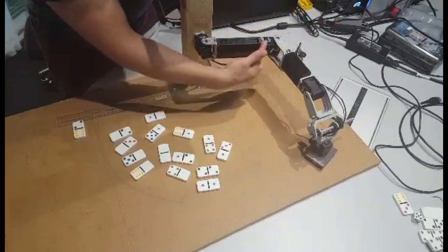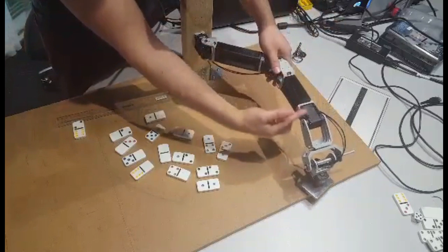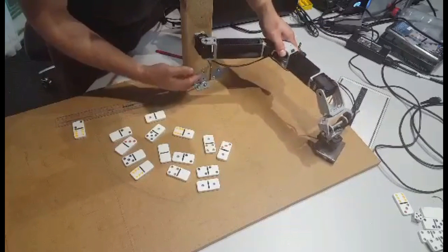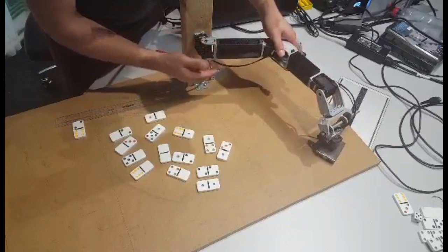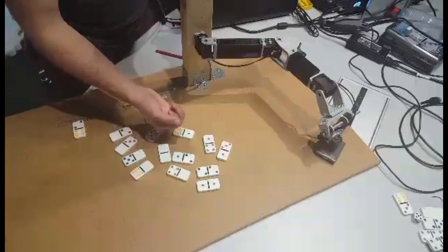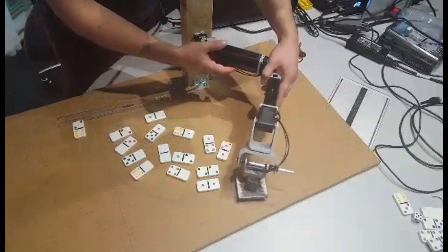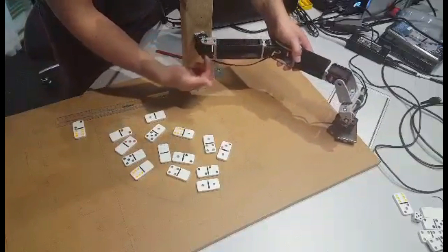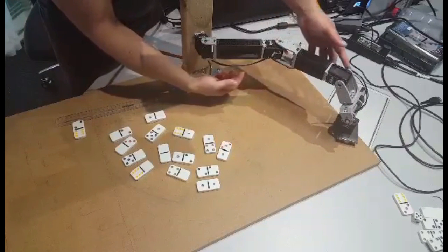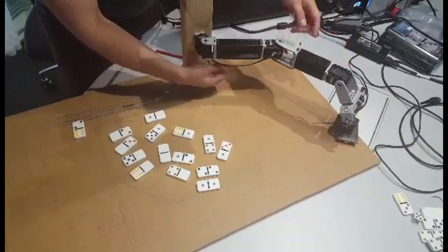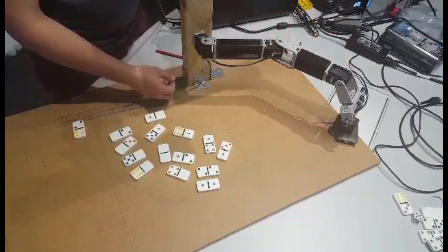Two 3D printed X-beam pieces were designed for having a symmetrical moment of area in any horizontal orientation. Horizontal displacement is achieved by 176 and 246.5 mm links being rotated with respect to the vertical axis by motors 1 and 2.